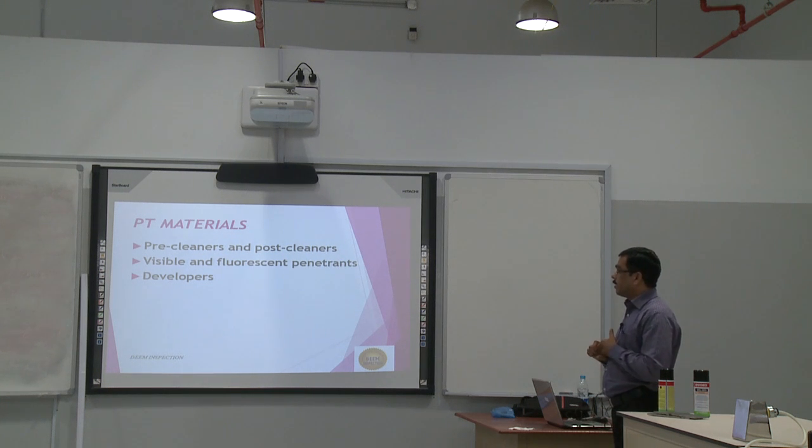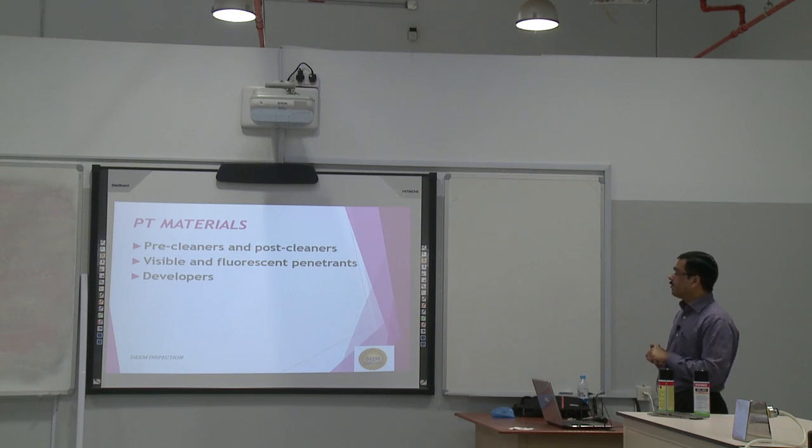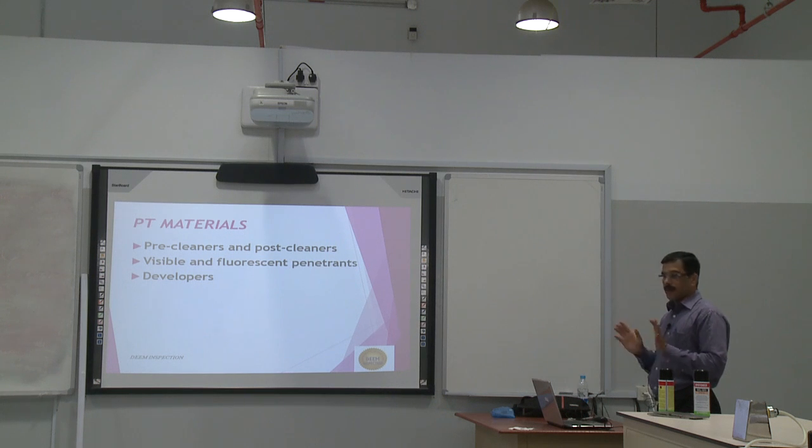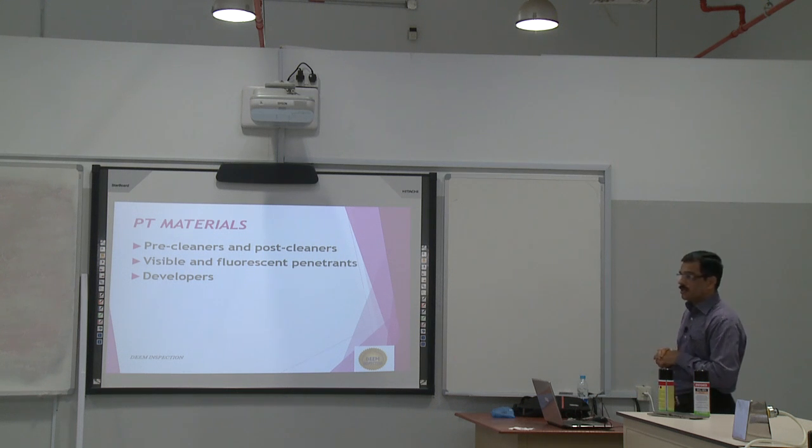We need a pre-cleaner and post-cleaner. Mostly we are using the same one. Visible and fluorescent penetrants, developers. So these are the 3 chemicals we require for penetrant testing.